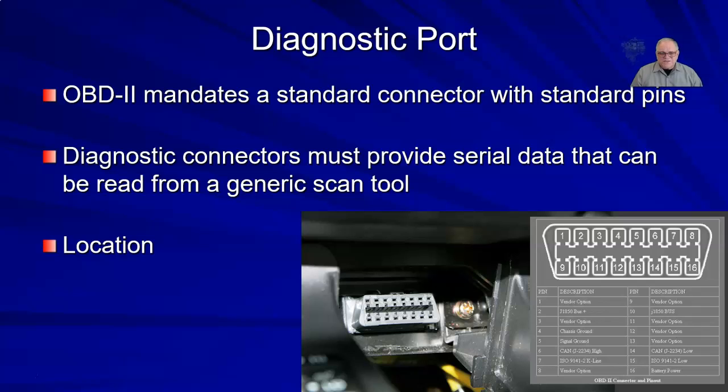If pin 16 is good, what I like to do is put a lab scope on there. I put my black lead to pin 5, which is a signal ground, one channel to pin 6, the other channel to pin 14, and watch to see that those two signals look like a mirror image of each other.